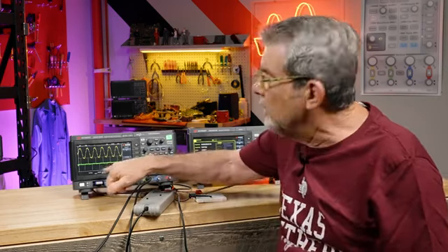Now you may be wondering about power, and you may have learned in your classes that power is voltage times current. But if you take the RMS voltage times the RMS current, that doesn't produce what's called real power. That's apparent power. And that would be about 43 volt amps, not watts. So what about real power?